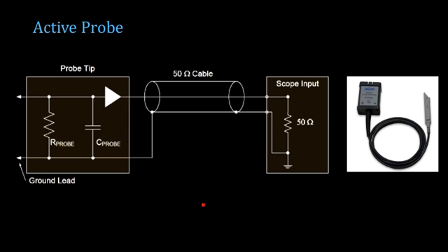So here this is your circuit for an active probe. So here you can see that a diode is being used here. You can replace this with a FET amplifier or any other amplifier, active components. You will be getting an active probe. So this is the probe end where you connect your circuit, and this is the end where you provide to the CRO or the oscilloscope.